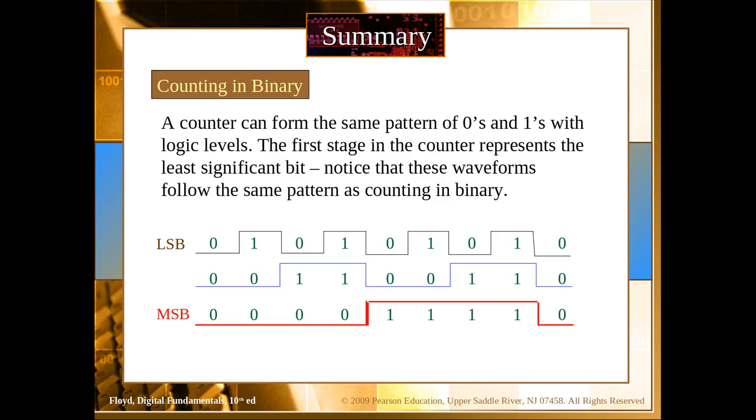Similarly, for the third bit the frequency is further halved, and every subsequent bit would change its frequency in half. That means we can use flip-flops in cascade, one after the other. And if you remember, flip-flops can be used as a frequency divider only if they are in the toggle mode.